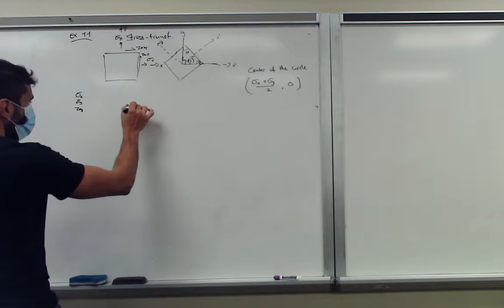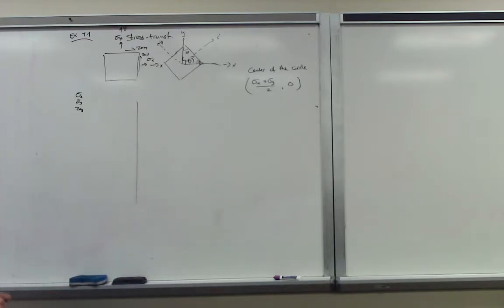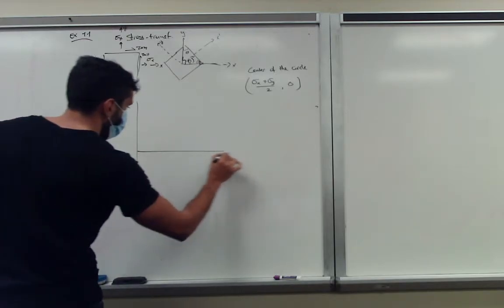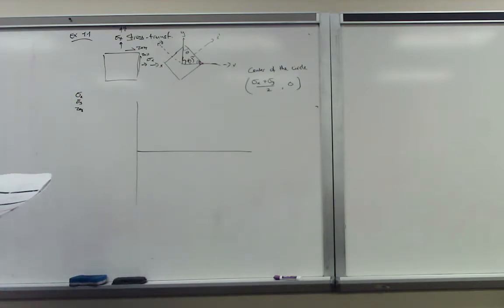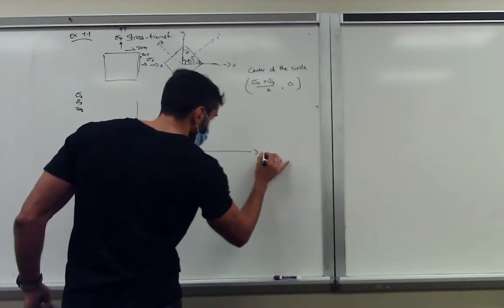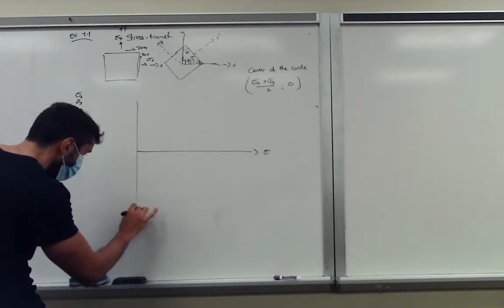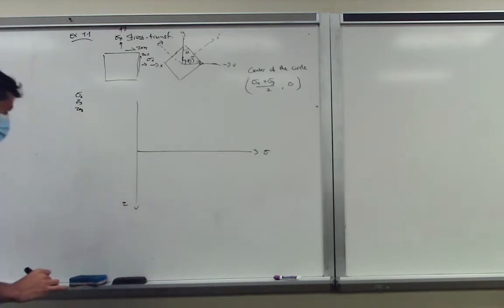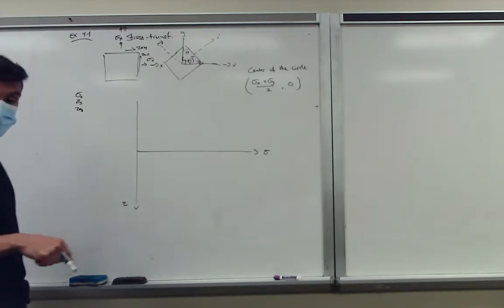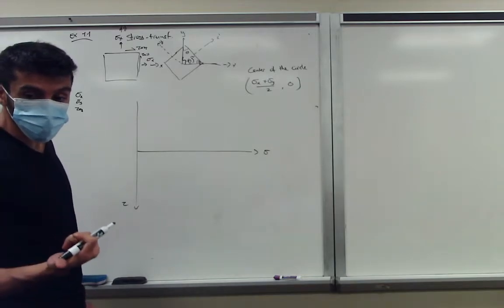So if we have our axes, on this axis we have our direct stresses, and on this axis we have our shear stresses. Notice that positive is defined downwards, not upwards like the figure says.